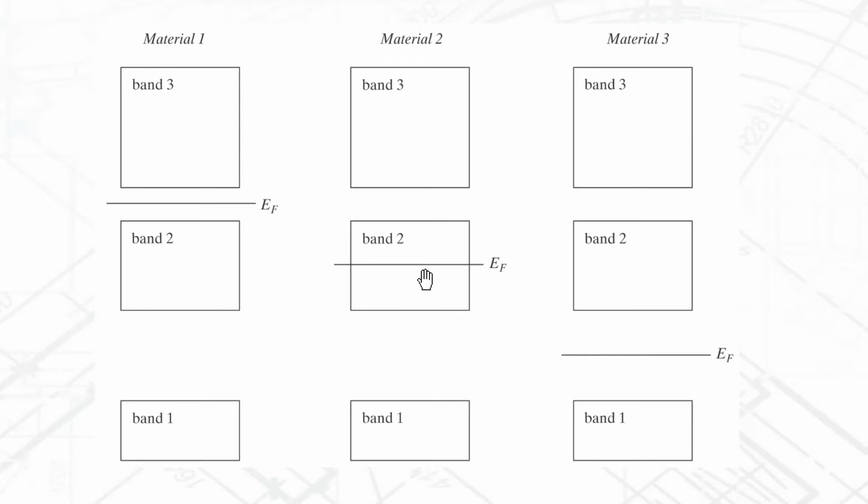Yeah, that means that these states below EF, there's a lot of electrons below EF, but most of the stuff above EF is empty. Very close to EF, there's a transition zone, right? The Fermi function transitions from 1 to 0 as you go through EF. But there's a bunch of empty states here, and there's a bunch of full states here, and there's this transition zone here.